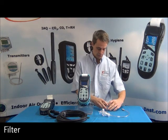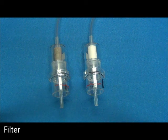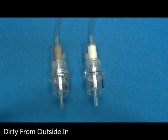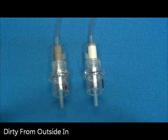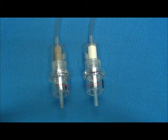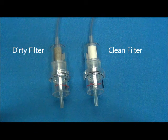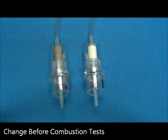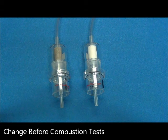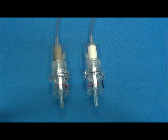Take a look at the filter next. Unlike some other analyzers, E-Instruments filter gets dirty from the outside in. This allows you to easily see any dirt buildup without having to take the assembly apart and look inside. If the filter has any cracks or heavy buildup of dust or particulates, change it before doing any combustion tests, preventing any of the combustion byproducts and particulates from getting pulled inside the analyzer.